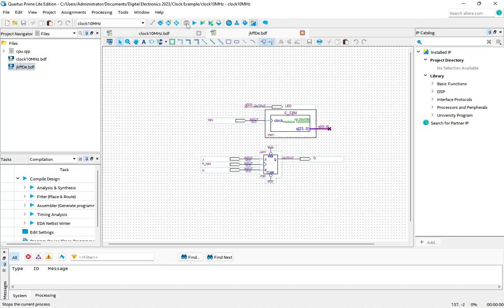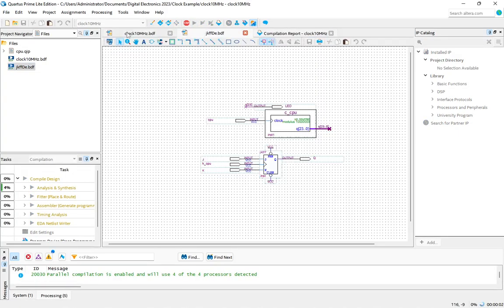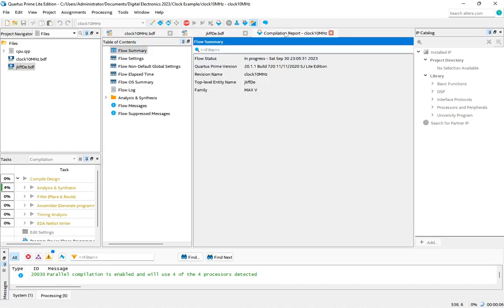So once you've done this, since you have two files here, and on your hierarchy it's specified that you're going to be executing clock megahertz, which is this file here, just right click on the one that you want to build and set as entry level. And then build. So that will build this one instead of that one we were working on the first time.